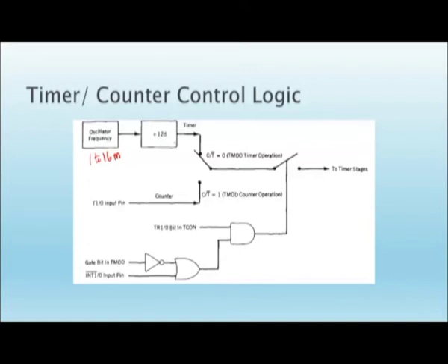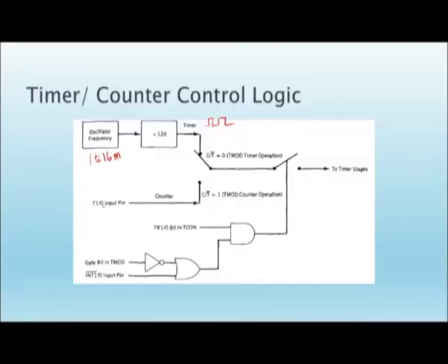That frequency is then internally divided by 12, because we want only a single pulse for 1 machine cycle. So, divided by 12, it gives the signal pulses. Here also we are getting the pulses for the timer. The other option is that, either in the T1 register or T0 register, we initialize some values, or externally we can connect some hardware devices to generate the pulses. So, based on this, the pulses are generated.